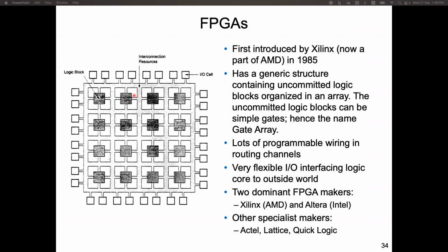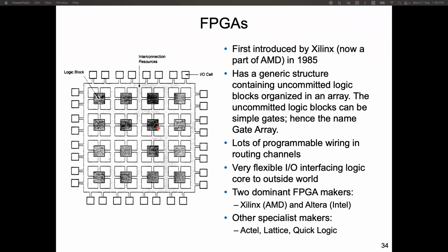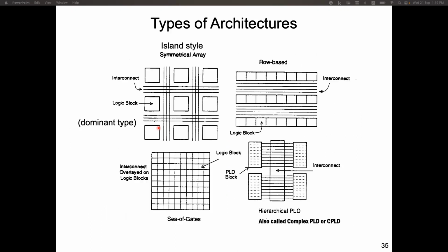So you see, in FPGA, we have two layers of programmable things. One is the logic, the second is the interconnection. Well, this architecture is one type of FPGA architecture. Some call it island type, or island style. We have a symmetrical array, like a matrix of logic elements, and the routing or interconnect are in between those islands, like building blocks and the roads.